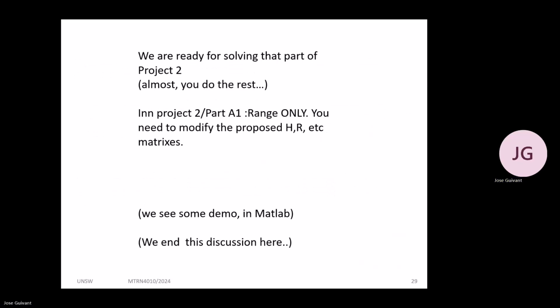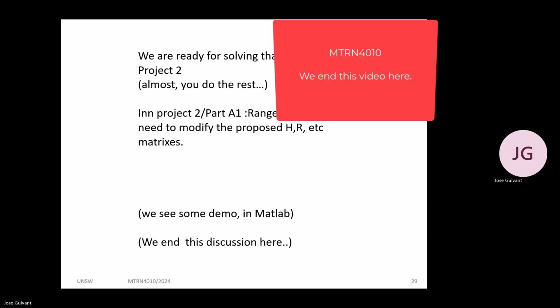All right. And that is what we needed to do for understanding this particular problem, which is localizing our platform, exploiting the LiDAR information, pretending that we have a sonar. So we just process the distance to the object of interest we are extracting. And also we are exploiting the kinematic model using as input the measurements we got from sensors, but we also consider that those sensors are introducing error. And we are going to see a demo, but that corresponds to a different video. We are going to stop this now, continue later.